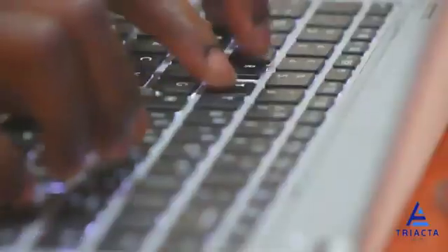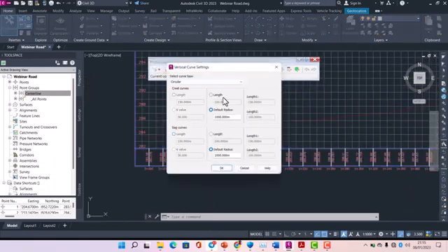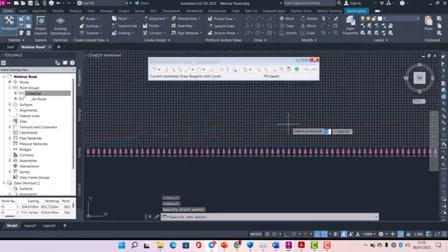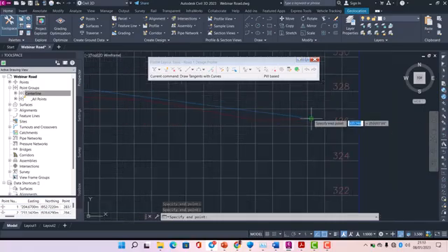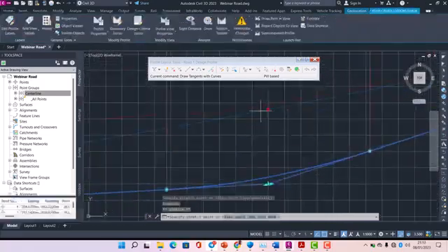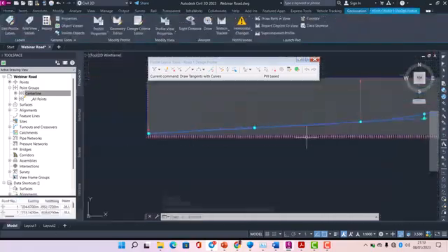So in this webinar, I have taken you through a comprehensive overview of the design of a highway using Civil3D. That is starting from importing your points through to your design, and then eventually extracting your design data for setting out on site. I've also shown you how to import your design codes that will automatically be checking your design while you are working on it.